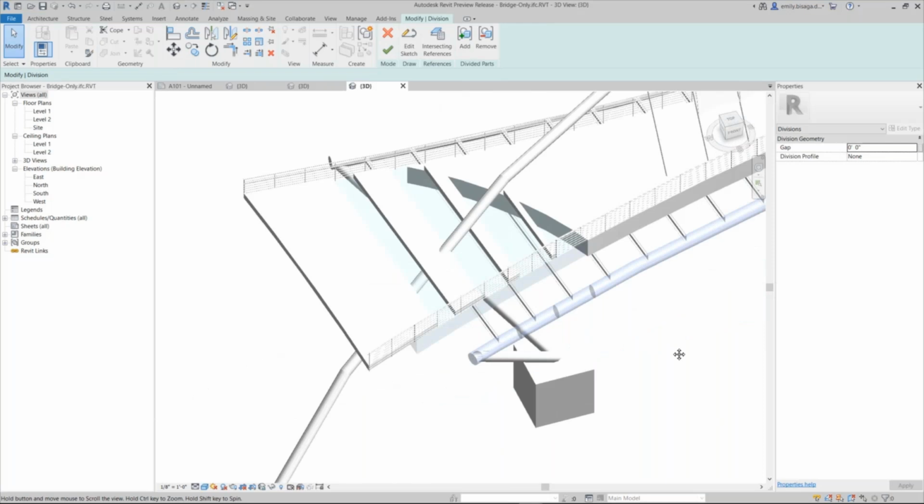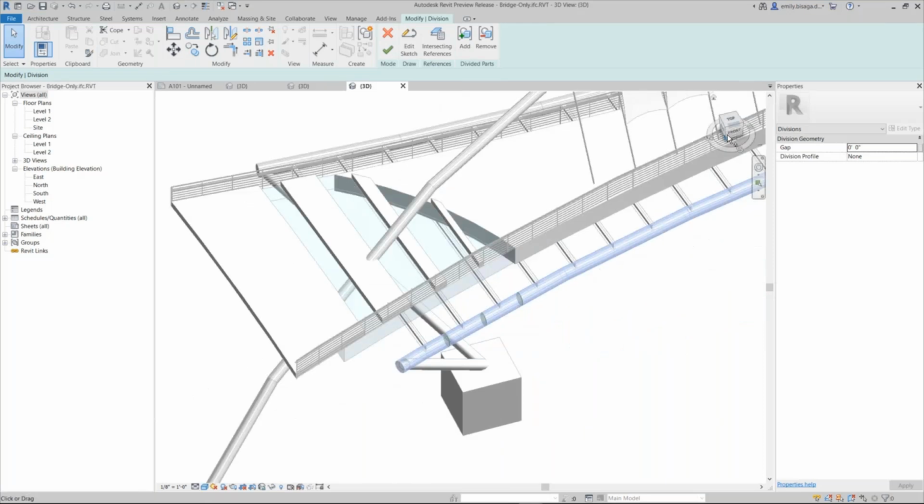So parts, which are mostly used many times in Revit, I can use on an IFC model as well. It's a good enhancement. So if I'm bringing a model from third-party software using an IFC import or something like that, I can really convert that into parts and use it further.